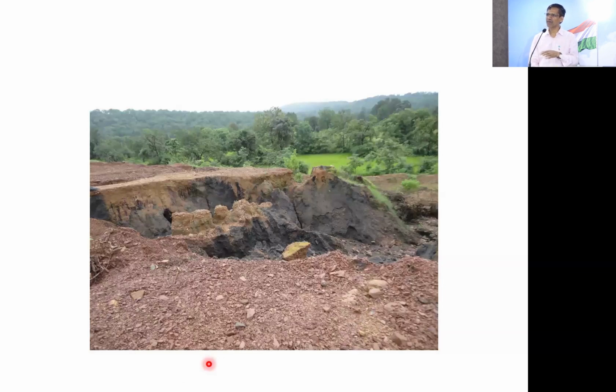The most important point was the soil properties, because with fly ash, this was also 2010, nearby in Chhattisgarh. That is what I first wanted to study. Fly ash does not have any cohesion, and the friction you are assuming is also a transient phenomenon.